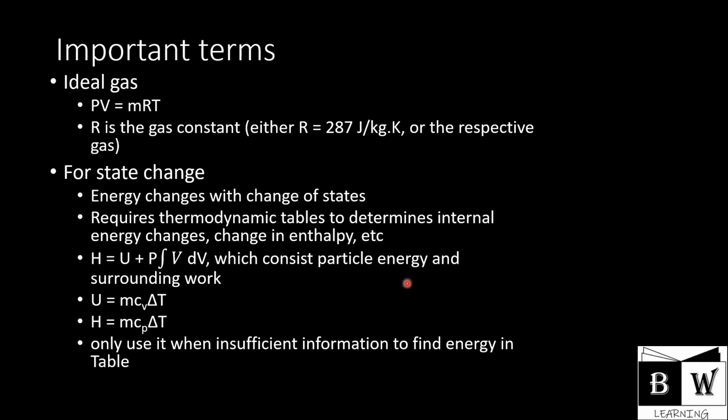So I mentioned enthalpy. Enthalpy is purely internal energy adding a constant pressure work that is happening in the surrounding of the system. So to give you some tips, if you have a closed tank, alright, a closed tank that's not going to be expanding or contracting, then use internal energy to solve your first law of thermodynamics. Else, if you have things that are flowing, like your refrigeration cycle, and your Rankine cycle, or even a piston cylinder, then please use enthalpy to solve your problem.